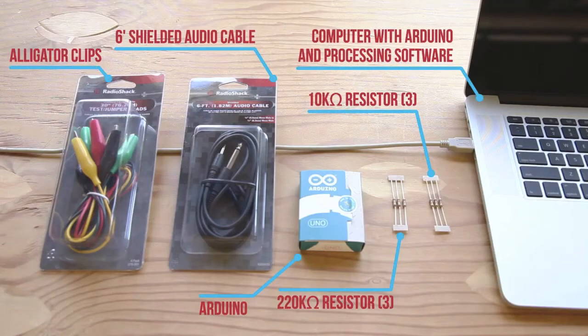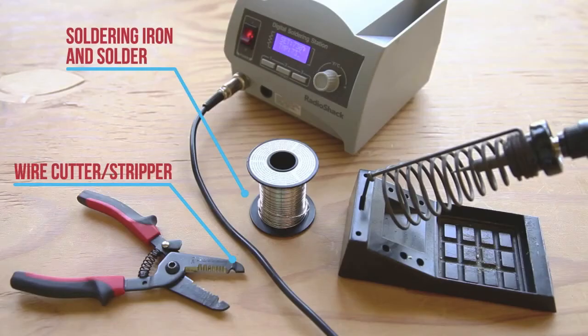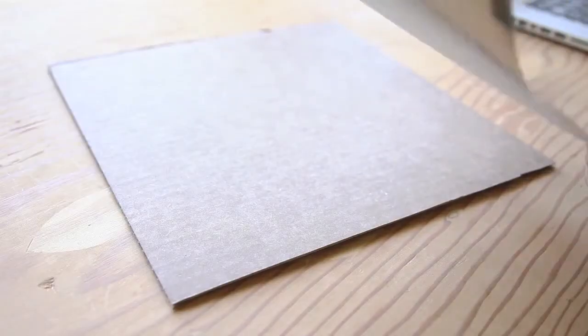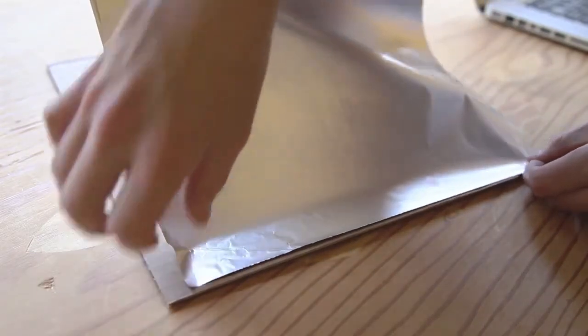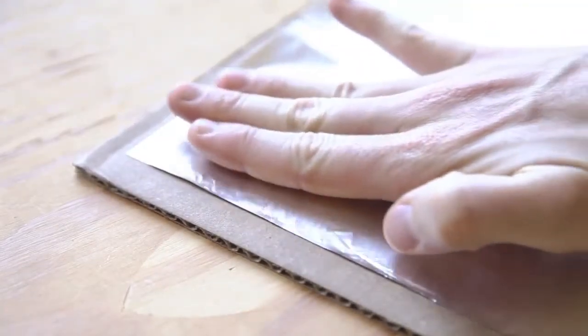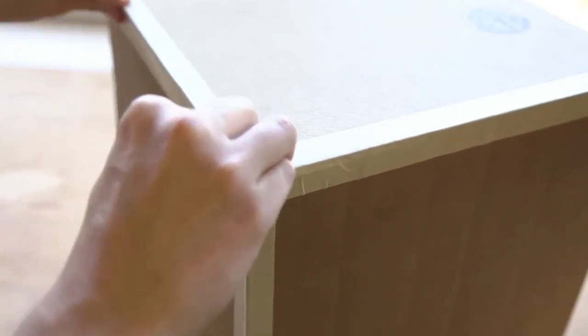Parts for this build. You will also need these tools. Start with 3 cardboard squares about 12 inches square. Attach 3 similar sized pieces of aluminum foil to one side of each square with spray glue or glue stick. Work slowly and make sure to leave a small gap around the edge of the foil. It is important that the foil plates do not touch each other when we tape the 3 sides together. Using tape, assemble the plates to form 1/2 of a cube.